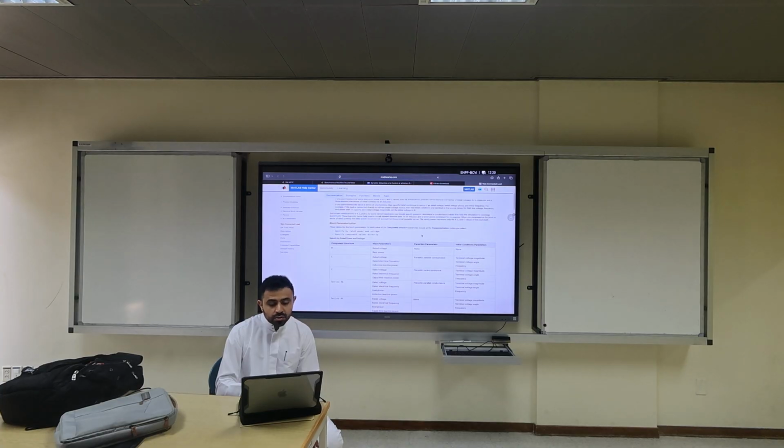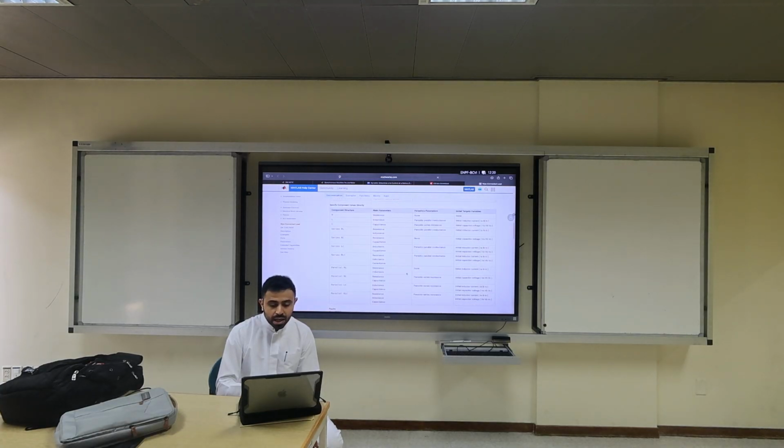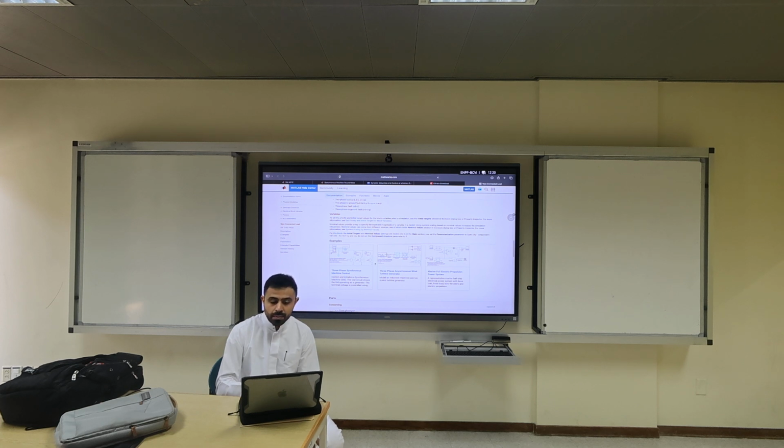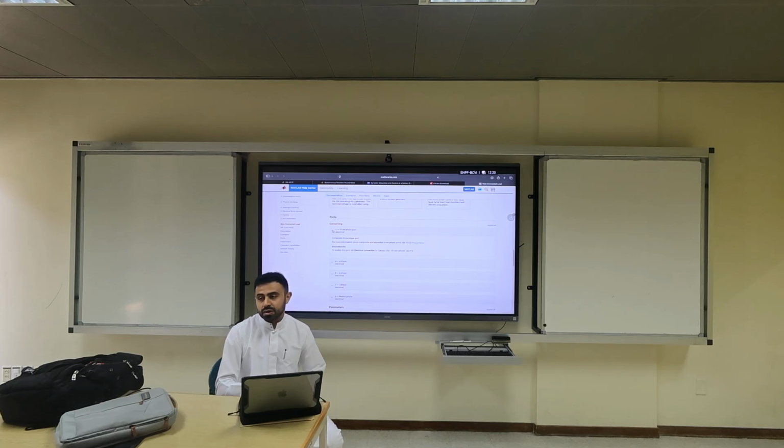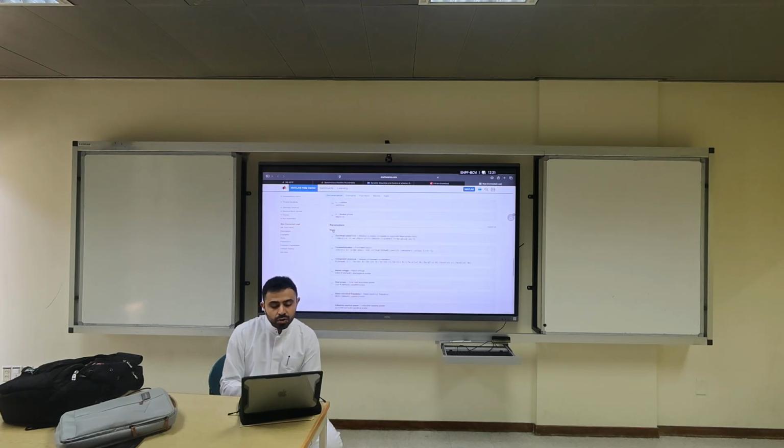And then here you read, for example, what the components are, relevant examples, ports, what it means in the IOs, the input and the output. So what inputs do we have? We have phase A, B, and C, and neutral, and we have one three-phase port. If you pass three signals, all of them together, you put it here. Then you read the parameters, the electrical connection, etc.